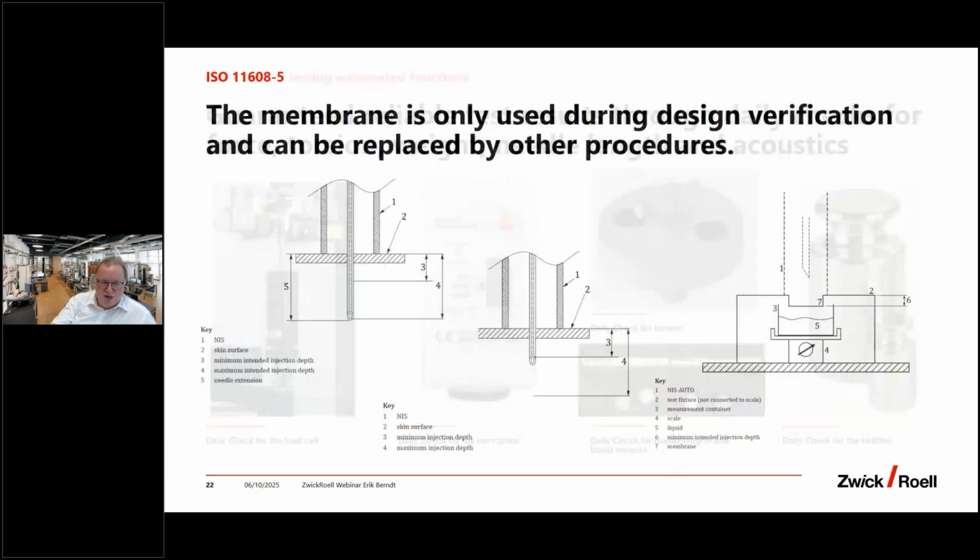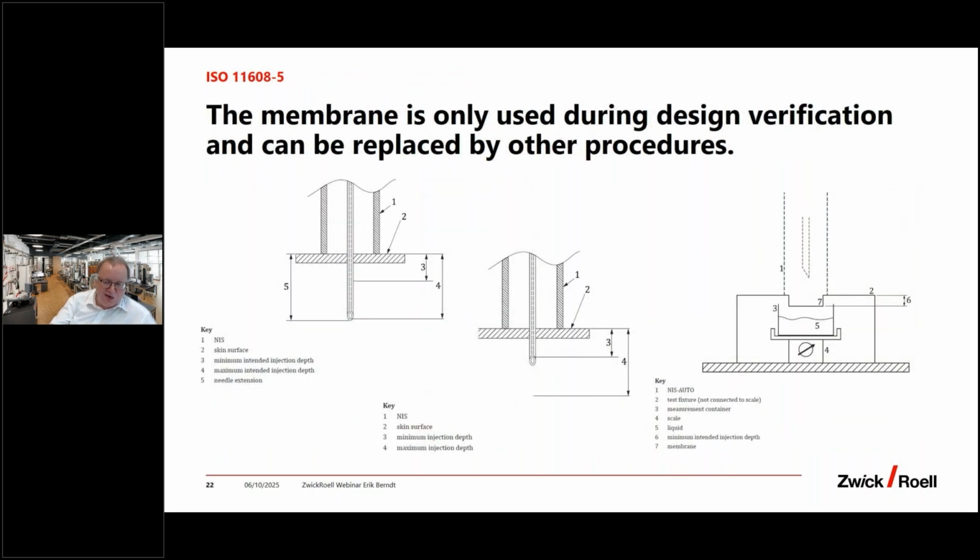Now, heading to a very discussed topic at the moment in the ISO 11608-5, and this is the topic of the testing with the membrane. At the end, I copied only 3 slides out of the standard. The discussion is going on the special intended injection depth. This means normally you want to do your injection between the maximum and the minimum intended injection depth, and you have to prove this in the design verification phase. And in the standard, it's written, it's explained.